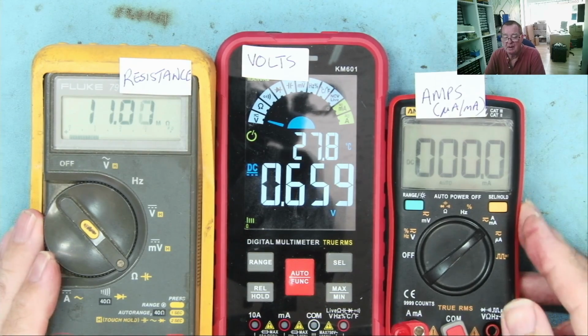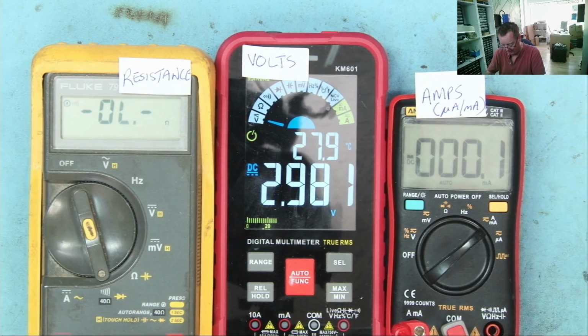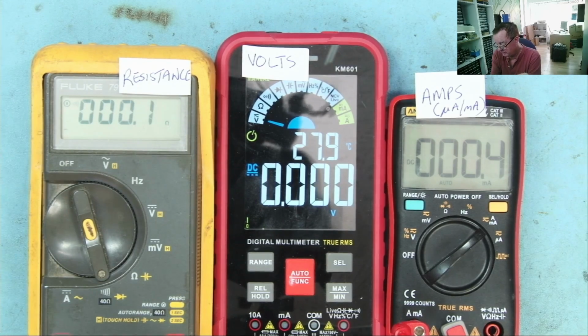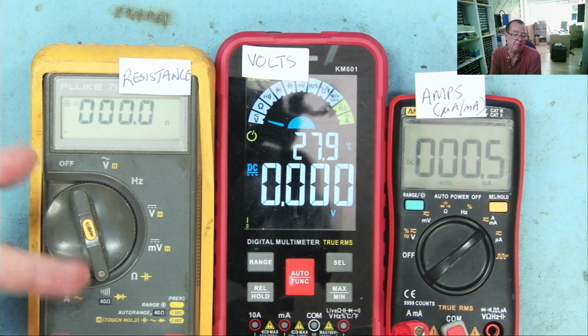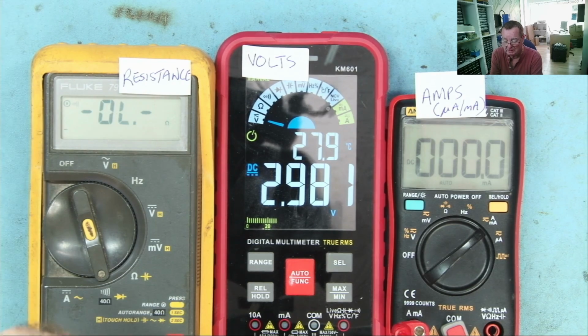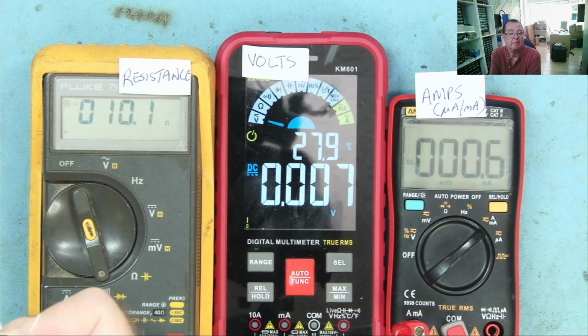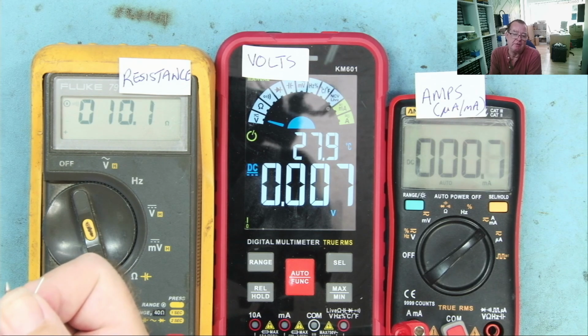Now let's have a look at continuity mode. So I'm just in continuity mode. I'm still in resistance, okay? We now get a bleep because I've switched the bleeper on, and this will measure up to about 40 ohms, it says, and bleep. So if we take our 10 ohm resistor again, connect it across our meter probes, you'll see we have the same sort of thing. It can't generate the 0.1 of a volt, but you'll see the voltage and the current in milliamps are relative to each other, and that's why we have 10 ohms.